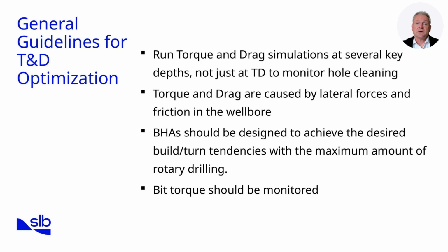Second, remember that torque and drag are caused by lateral forces and friction in the wellbore. Lateral forces increase with inclination, doglegs, and borehole roughness, while friction is influenced by formation, contact, and mud lubricity. Recognizing both contributions is essential when diagnosing problems. Third, the BHA should be designed to achieve the required build or turn tendencies with maximum rotary drilling. Sliding increases drag and torque unpredictability, so designs that minimize sliding improve efficiency and hole condition.